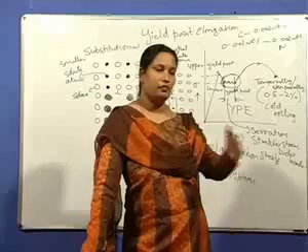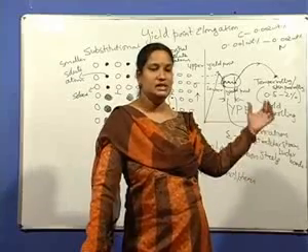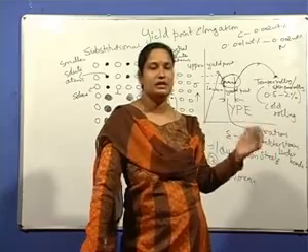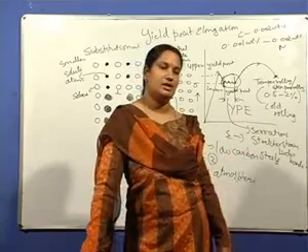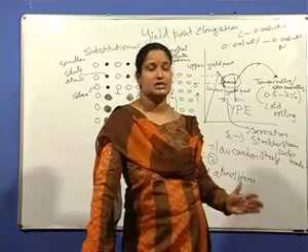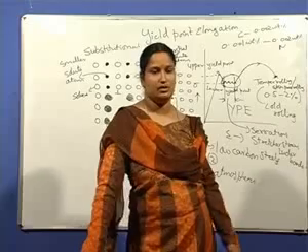The reason is, with time, these carbon and nitrogen interstitial alloying elements diffuse into the material again and form atmospheres. This is known as strain aging.